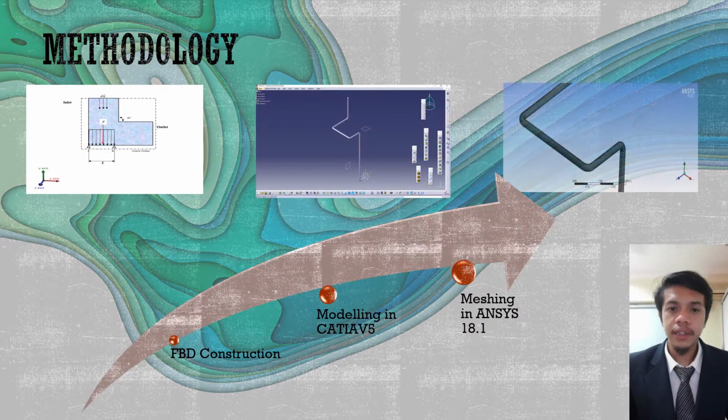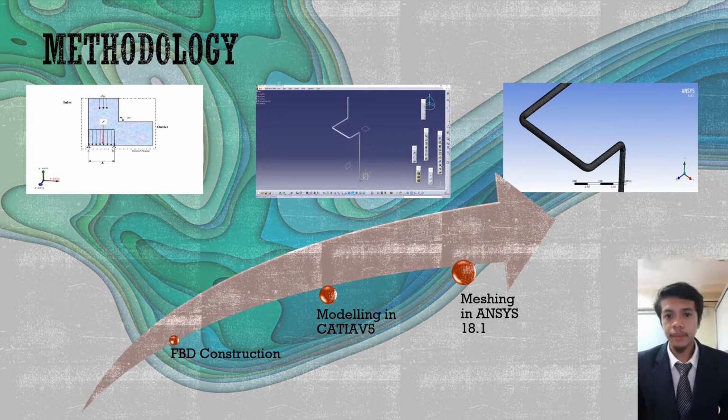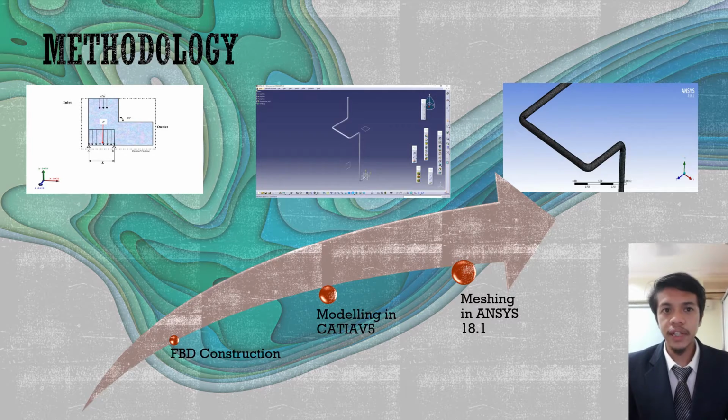Referring to the earlier free body diagram, the downcomer structure will be designed in the CAD software accordingly with its dimensions as per industrial use. Later on, the design will be imported into the ANSYS Design Modeler, whereas the inlet and outlet will also be specified in the meshing process. The nodes and elements for the meshing process were proposed to be at a value of 72,000 until 200,000 and not exceeding 1 million respectively.